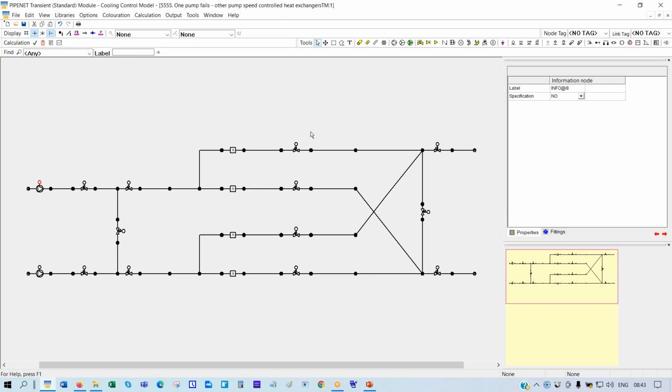Okay, and these are control valves. In the standard module, we did not have dynamic control loops. We simply said the control loop will be such that this valve should maintain a flow rate. That's all we said. But for dynamic analysis, you need to know the characteristics of the control loop, such as the PID controller and so on.